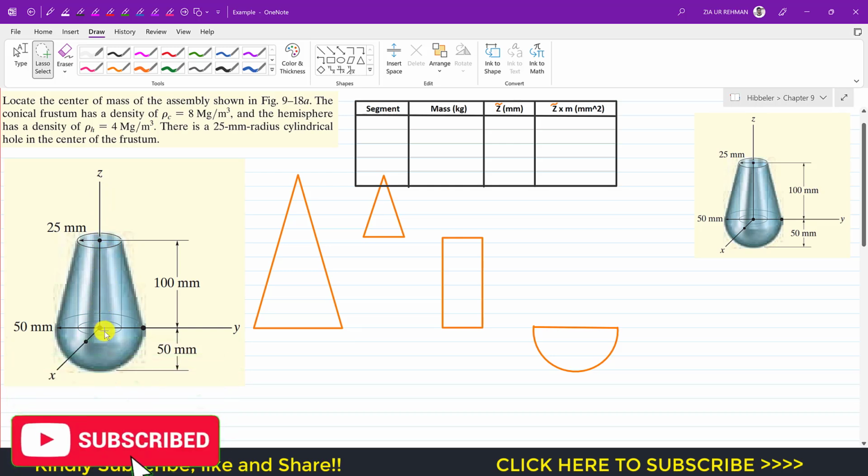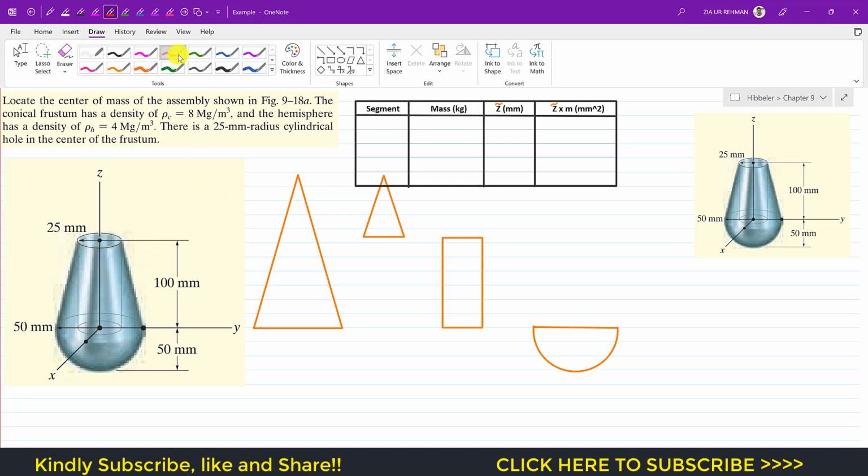Further, if we look into this whole composite body, it is symmetrical about the z-axis. So from that we can say that the centroid or the center of mass of this whole body will lie somewhere on the z-axis. So we can conclude that the x bar and y bar of the center of mass of this composite body will be equal to 0. So we only require to find the z bar, since this whole composite body is symmetrical about the z-axis.